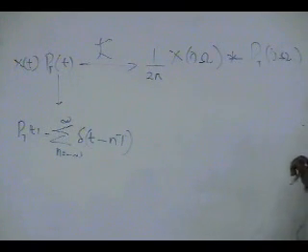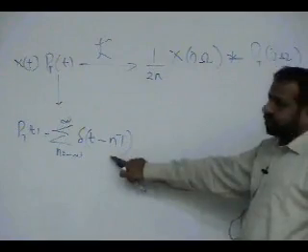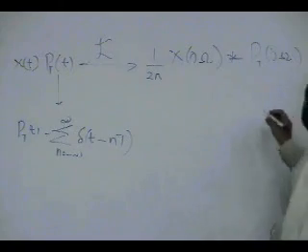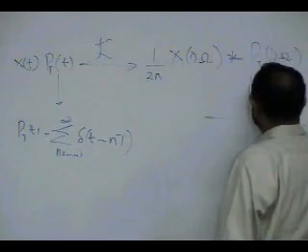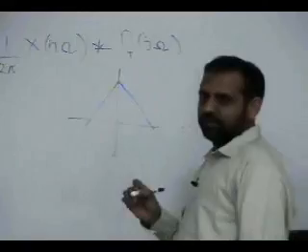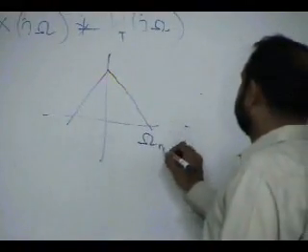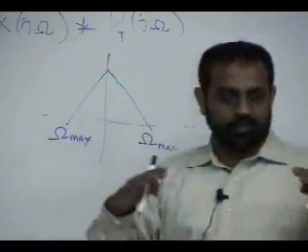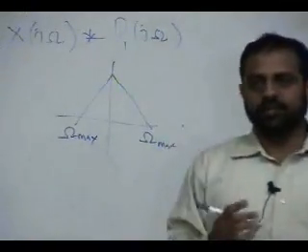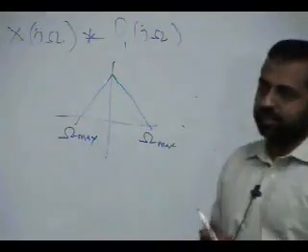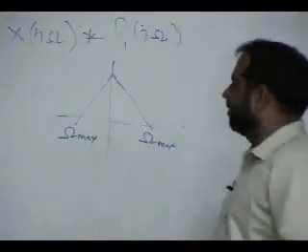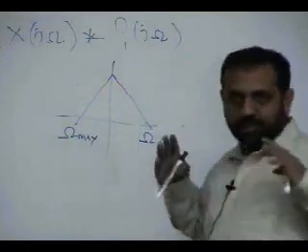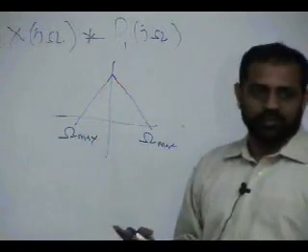How the Fourier transform of x of t looks is the signal. All you need to make sure is that it is a band limited signal, meaning you can only sample a band limited signal. So you need to make sure that it is curtailed to some maximum frequency, so there is nothing beyond a particular frequency in your signal. That is the way you can sample a signal. You cannot sample an infinite bandwidth signal, so it has got to be a band limited signal.